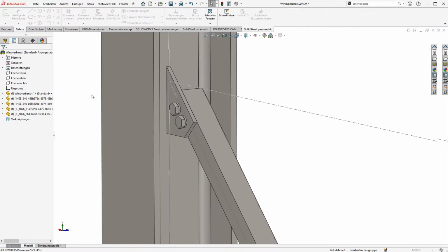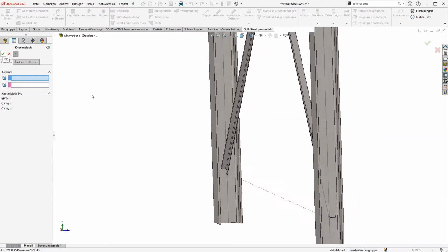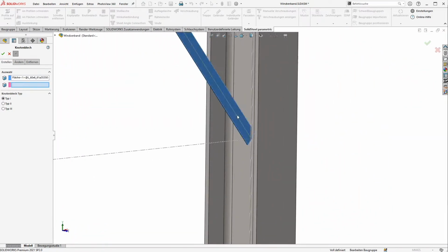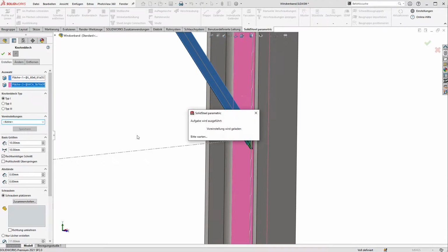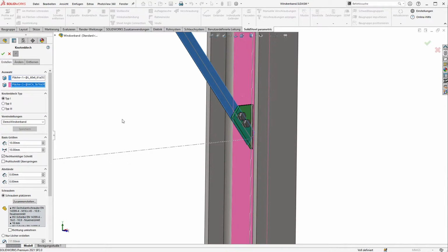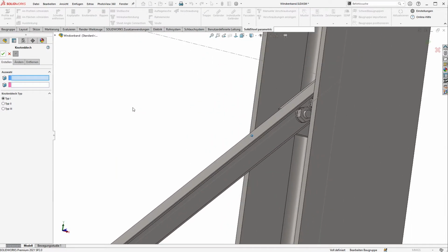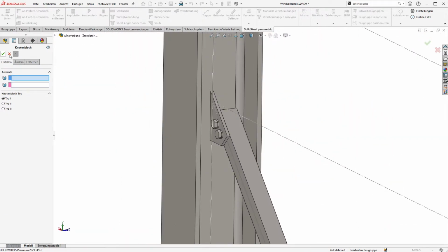This now with the other gussets in fast forward. We do not need to calculate separately that the gusset plates can withstand the load, because the critical geometries are exactly the same as for the diagonals, only with greater material thickness, so we are on the safe side. The question if the welded connection of the gusset plate to the support is also able to withstand the load cannot be answered with the same degree of certainty.